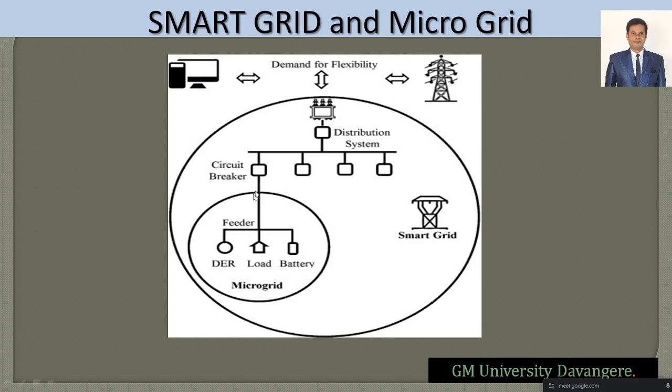Once the circuit breaker gets isolated, when isolation happens, what will happen to the load? Load is disconnected, no? See, now you are not to disconnect the loads, you have to restore them back. So that is called the black start. Black start will happen only from the batteries. We have the battery backup, no? We have the solar panel and wind panel, that is also failed. We have the battery backup. Through the battery backup, we are going to restore their loads.